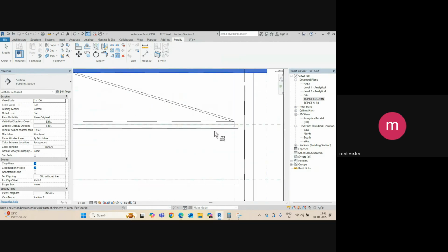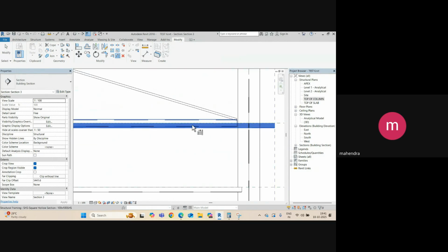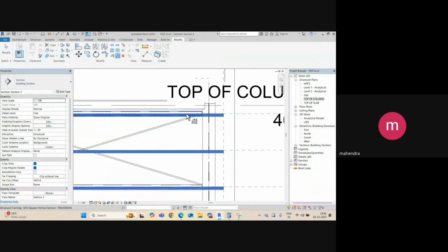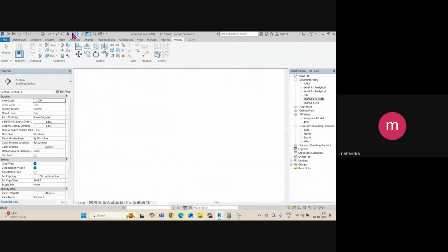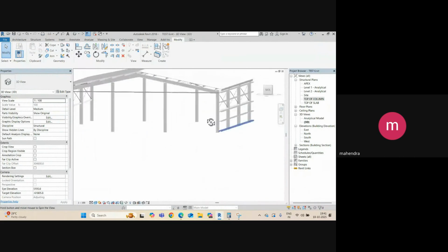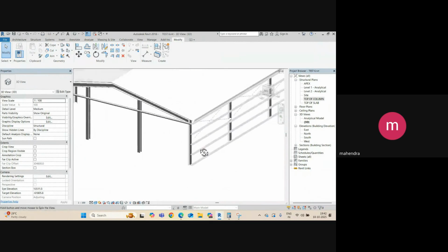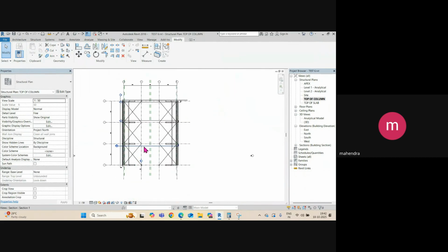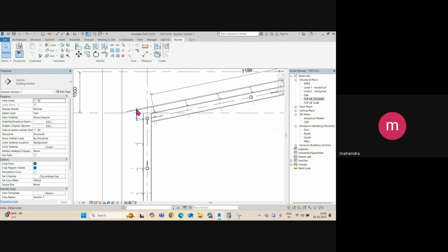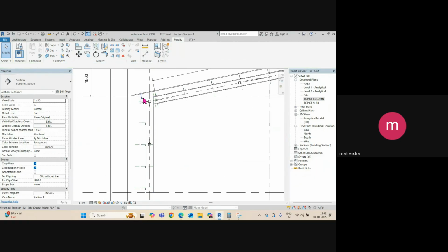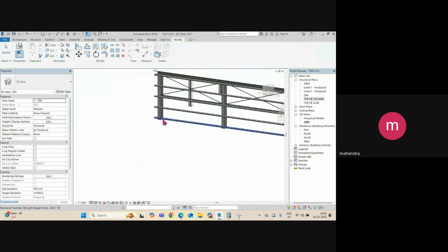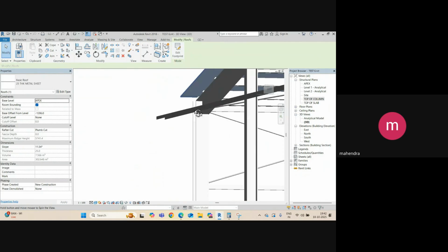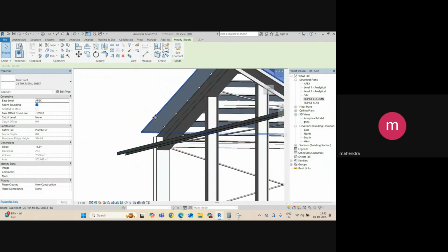One thing you need to check. This is our Z purlin, sorry, side guards here and one more here. If you look at it in 3D view, it's perfectly here, right? Once you have added this, you can just mirror to the opposite direction. Go to view and select. You need to modify this also. Yes, these side guards.